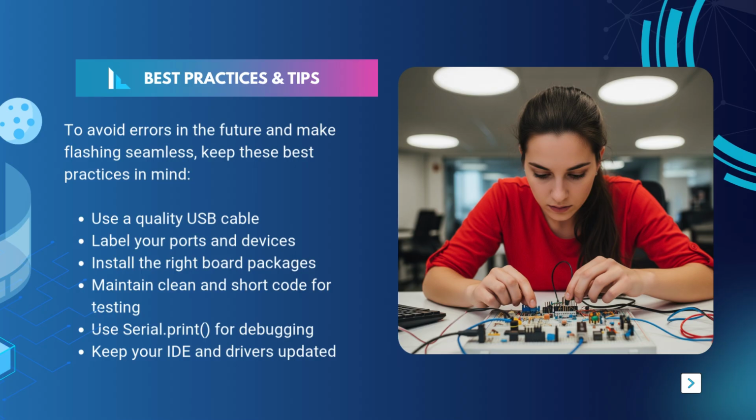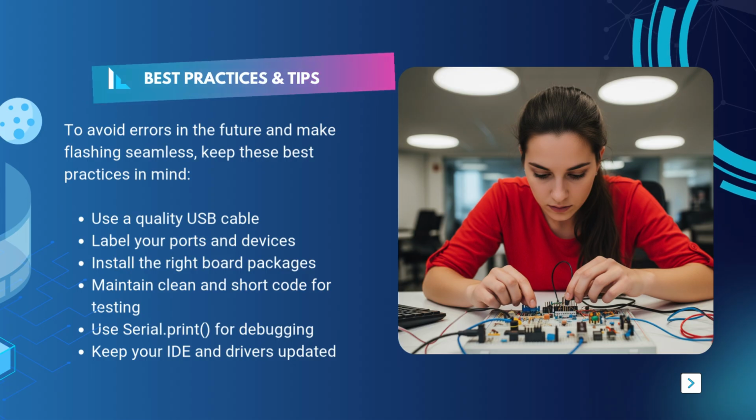Debug with serial monitor, print useful messages at each stage of your code. Back up your code, use Git or folders to avoid losing working versions. These tips not only help you flash successfully but also make your entire embedded development journey smoother and more professional.